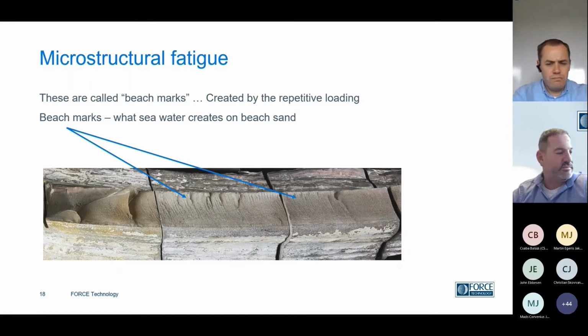Isn't the fatigue life of a structure defined until crack initiation? Yeah, another good question. No, because it's one of the things that needs to be discussed, but normally during testing, we will look at it from the other way. We will either wait for a certain amount of cycles to occur and then stop the test, or we'll wait for a through crack to occur.